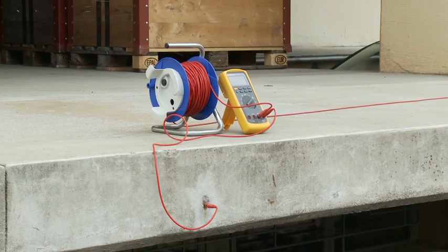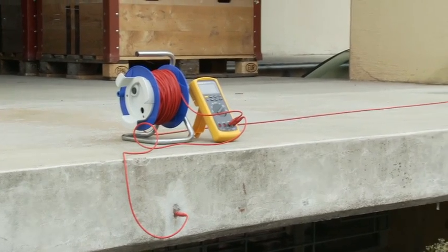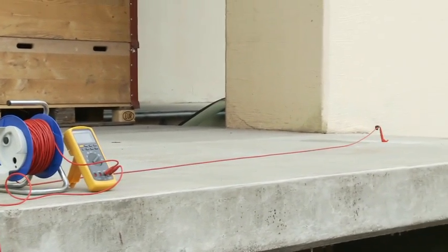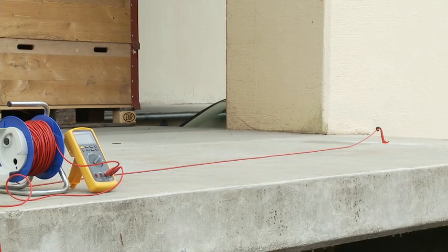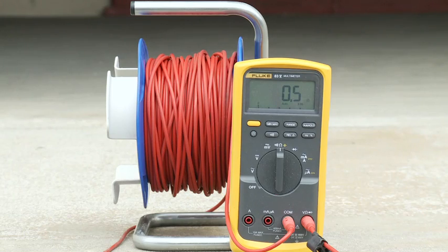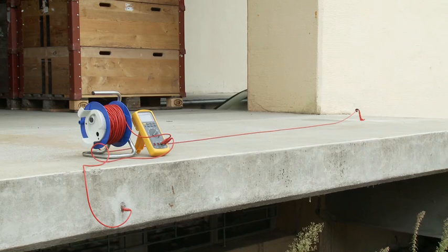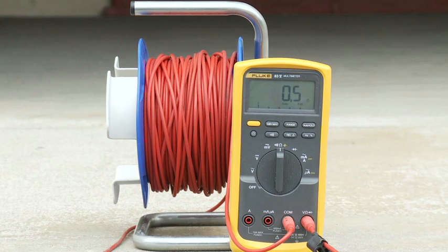The connection should be tested for continuity. This requires at least one other point of the reinforcement to be exposed and to check the resistance between the two with an ohm meter. The connection should be situated as far as possible in opposing corners of the surface under test. The measured resistance should not be more than 1 ohm above the resistance of the cable used.